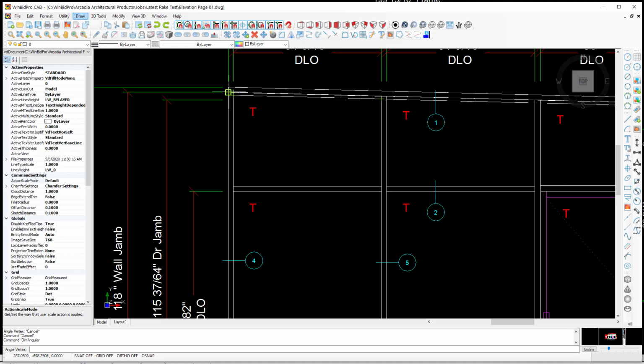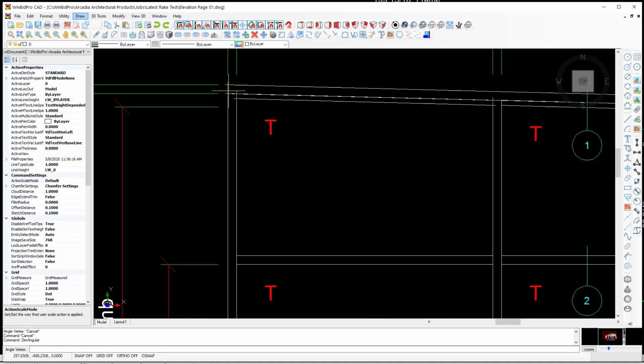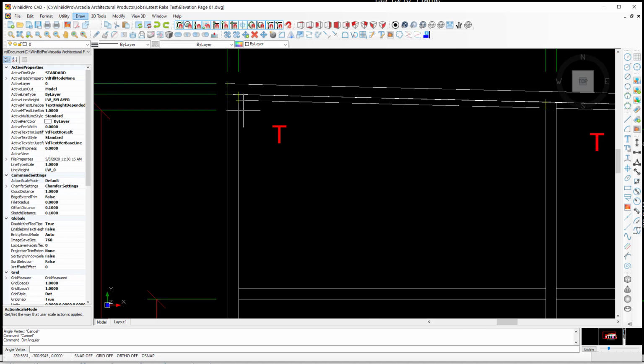With this particular command, we need to zoom in and pick the corner point first. And it gives me this little square icon. So now I can click. And now I'm going to go down and click on the axes that I want this dimension to be applied to. It's snapping to that line, which is what I want it to do, and it's snapping to it here. Now we've got our dimension. So I'm going to click one more time, and it solidifies or places that dimension.